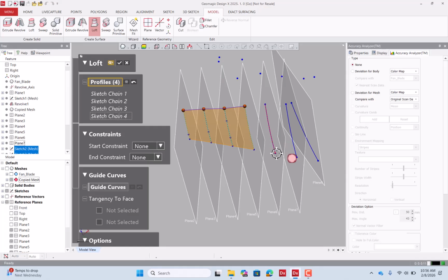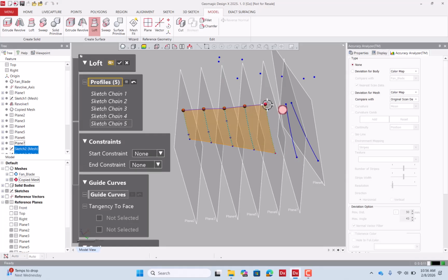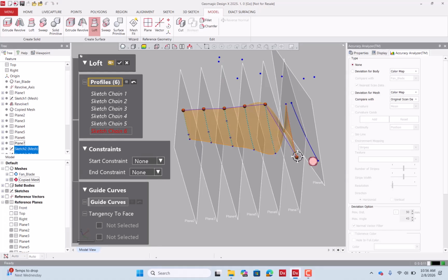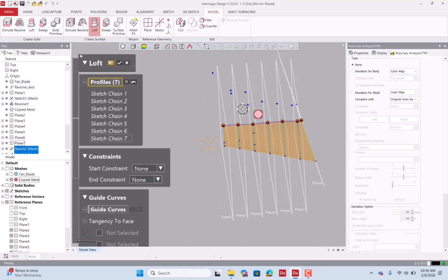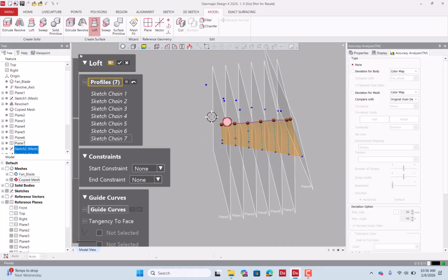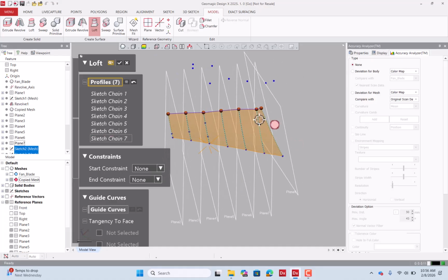So in other words, if I select a point here, it's going to select it correctly in the same orientation. Then if I select another point accidentally on this side, please do not worry, just click on that ball again. And I'm selecting another particular profile. So here we have made a lofted surface going across these profiles.